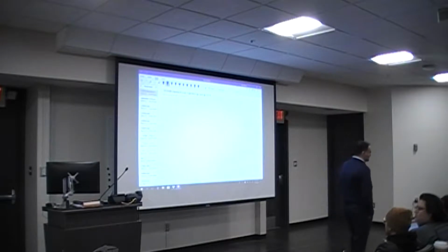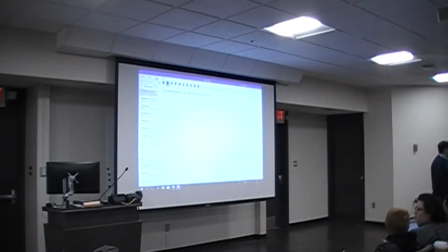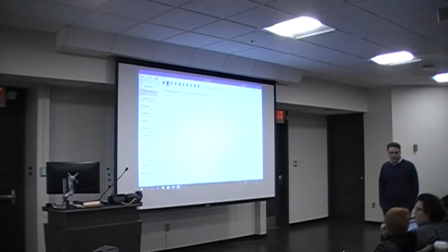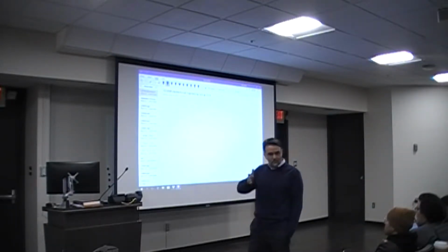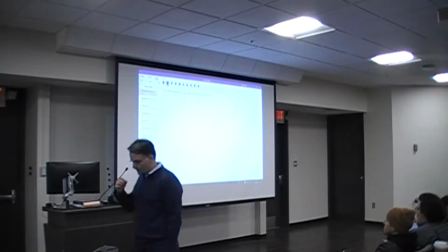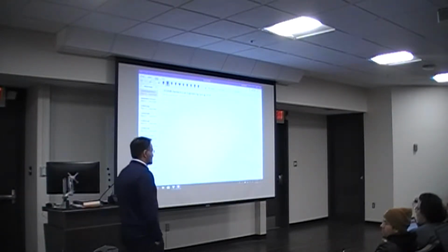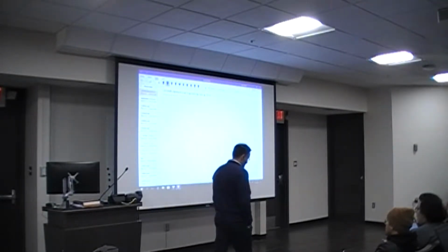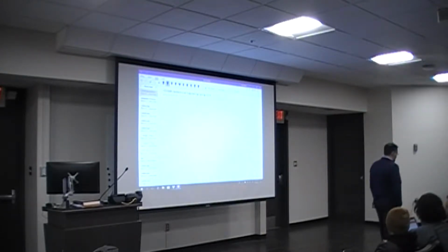We talked about the settlement analysis, and essentially what you have to do is plot the information relevant to the stiffness properties, or the stresses, in fact, as a function of changes in the void ratio. So you have void ratio on the y-axis, and you have the log of sigma prime, which is the log of the stresses, and that shows you the changes in the stiffness properties associated with the changes in the void ratio, and how you can correlate that to the settlement analysis. That would be your chapter 9.